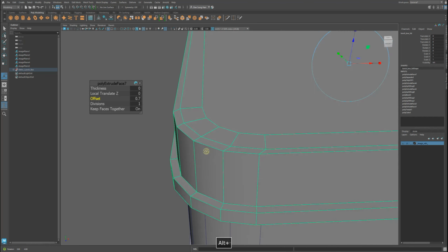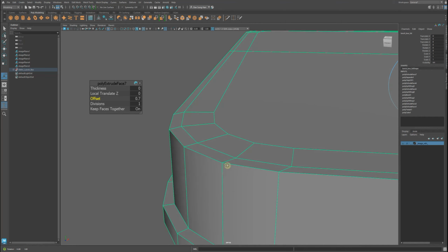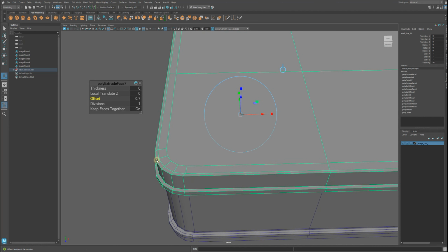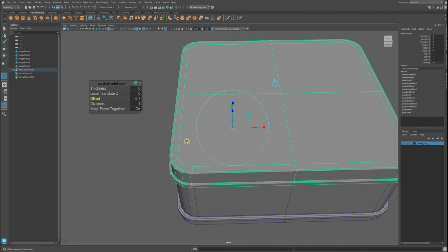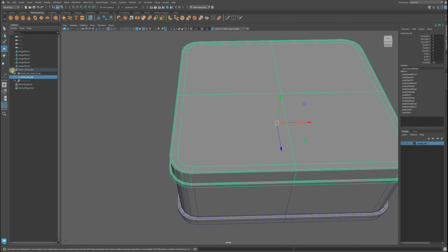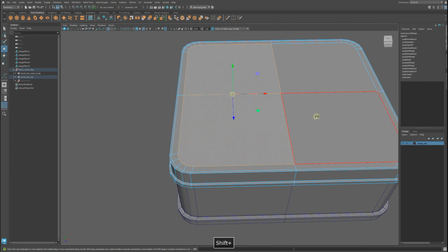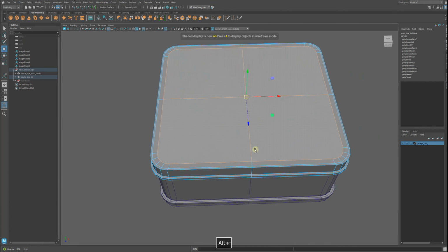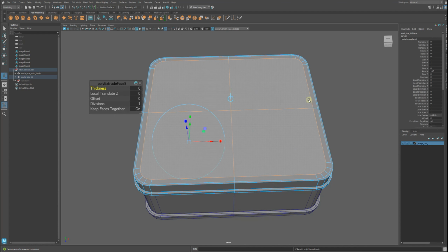There's a reason why. There's something called the rule of three, and I'll show some more regarding that. So this is 1, 2. I'm gonna make a third one like that. So from here, I'm gonna just click outside. I'm gonna reselect it. I'm gonna open this lunchbox, and just the lid. Right click, face. Select. Press 4. Press 5. Shift, right click, extrude, and do another offset, 0.1.